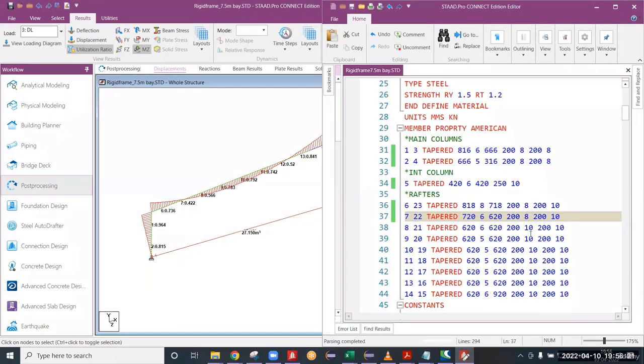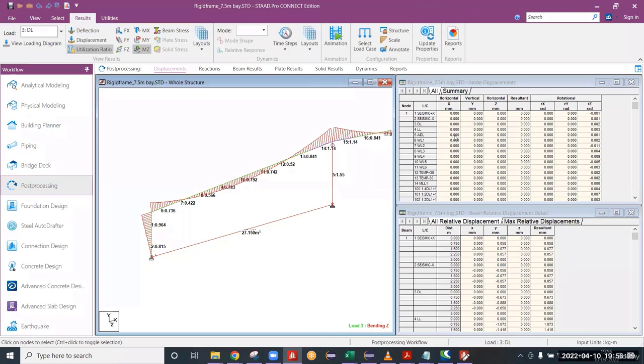Any other structure where it is not acceptable? If you go to conventional steel, you have to go with hot rolled members only. All these we are doing here are welded plate I sections. If you go to conventional steel structures, those are made up of hot rolled sections only. Hot rolled sections are sections with the same dimensions at top and bottom.